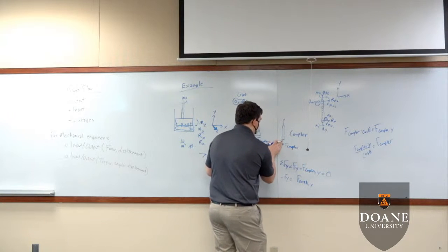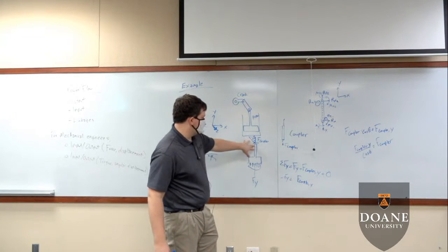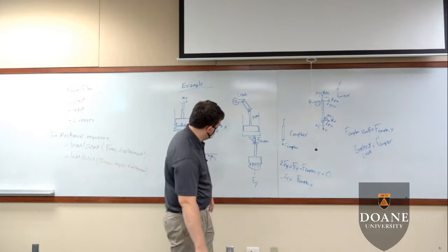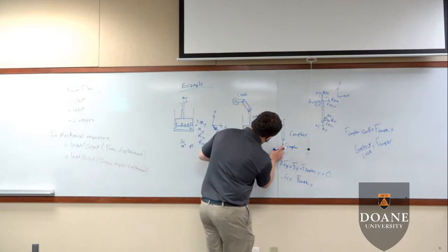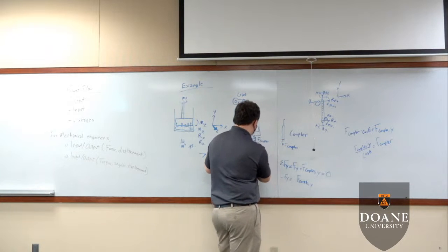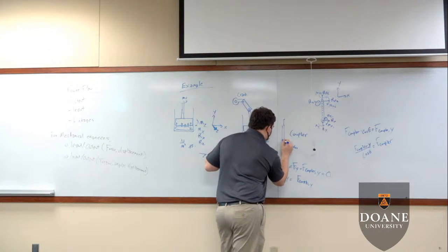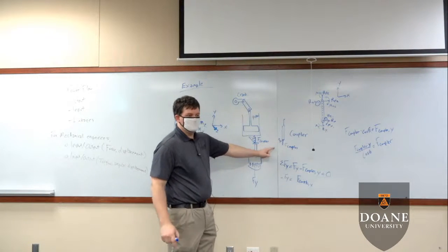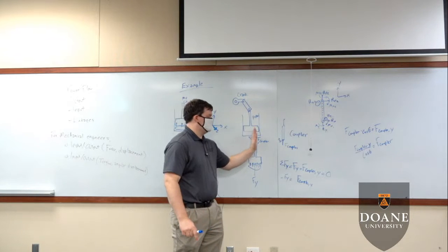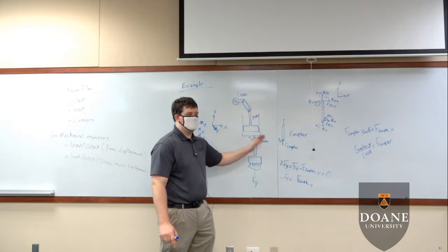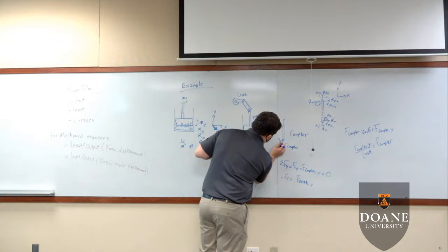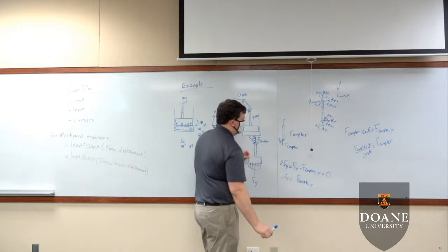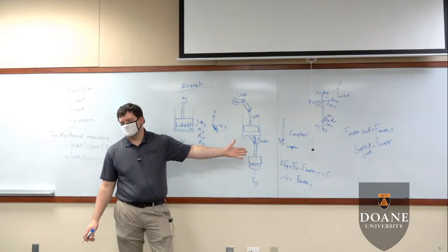And we know that here, if we were to model this force over here, okay, then what we have is, first of all, this is a compressive force now. I'm going to go ahead and change this to being in compression. The actual force, F couple Y, is coming in at that angle, because that's the angle that the piston head meets the coupler. The x component of that force has to be perpendicular, so it forms a triangle that looks like that.